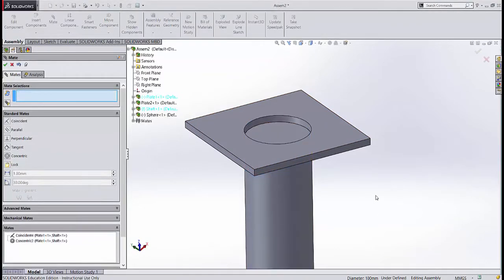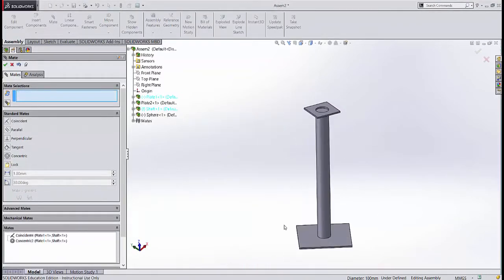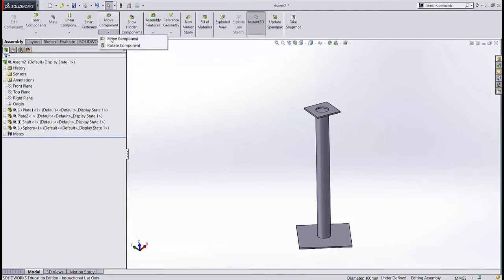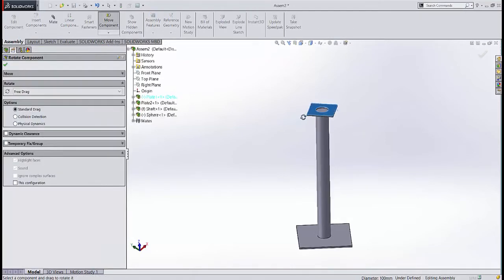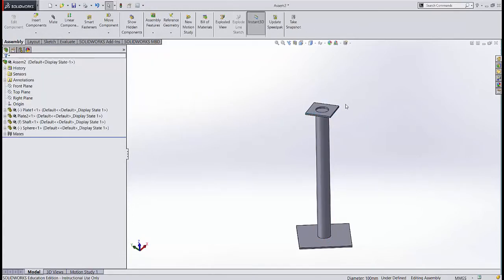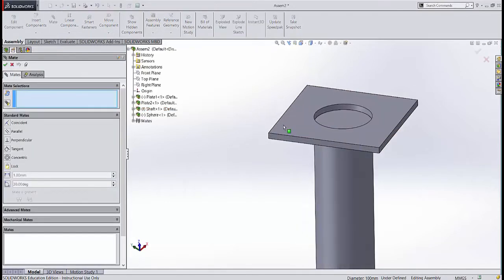And click OK. Now if we want to set the relative rotational degree of freedom, which we can verify exists by attempting to rotate this component, we can do so either by repeating the procedure shown before, which creates mates between the reference planes that exist in the reference coordinate system local to each part, or we can create a mate, for example, that exists between